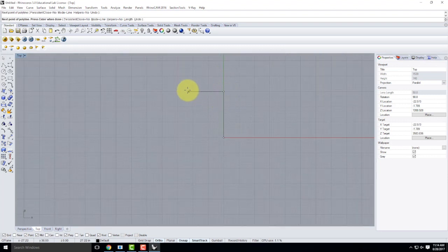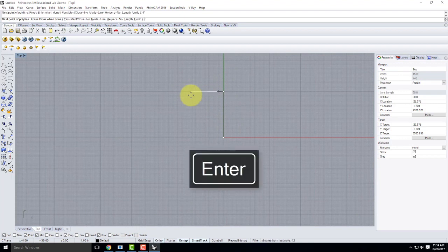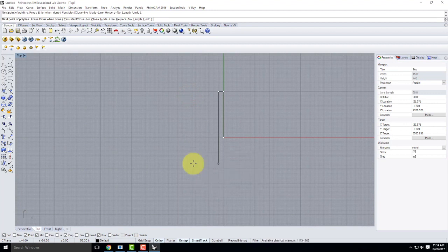After I've drawn that straight line, I'm going to move over in this direction by 4 inches, like that. Now, here is a perfect opportunity where, as you're just drawing naturally in Rhino, using relative coordinates is relevant. So far I've just done distance and direction.